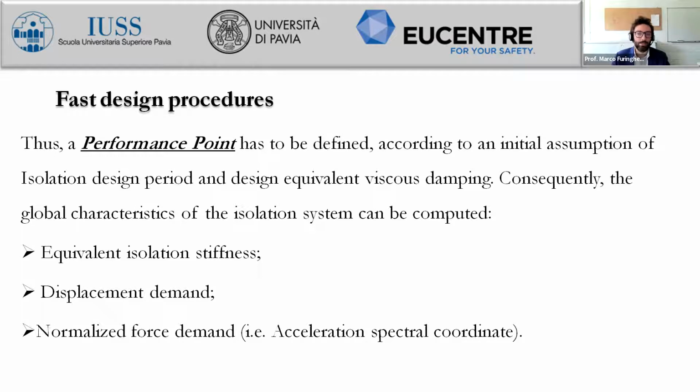And we have also seen that the damping ratio can be considered a constant value for rubber bearings, since we generally design the devices for a shear strain higher than or equal to 100%, which is the key value for designing rubber bearings and also lead rubber bearings.